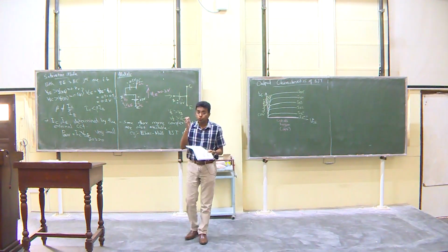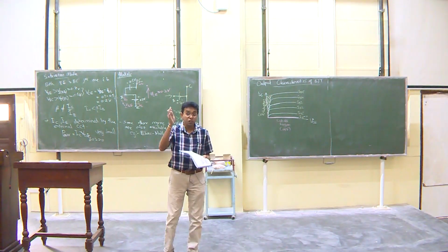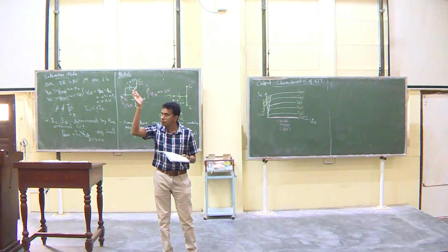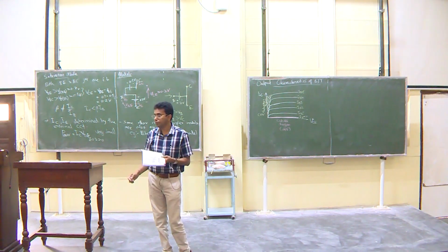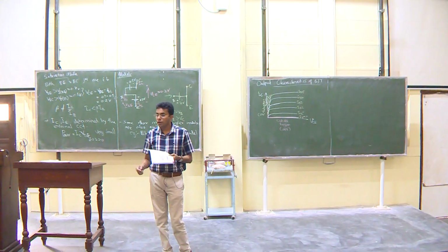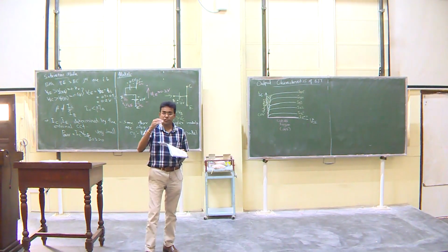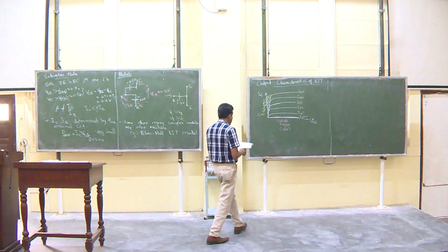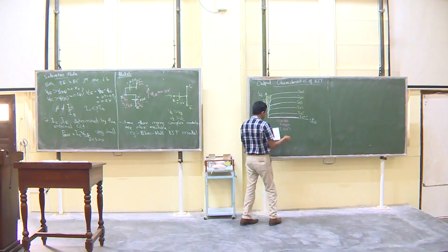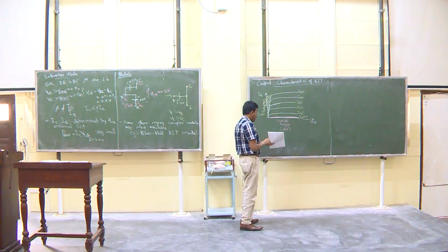If we are going to use the transistor as a switch, on-off switch, to control the current, this is the mode you will be working on, right? In such situations, either voltage is very small or current is very small. In between this area, we call this the active linear region.